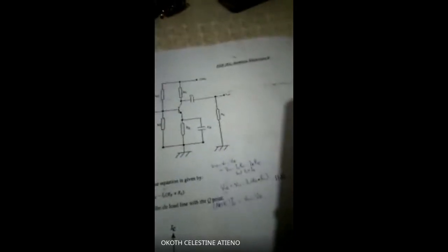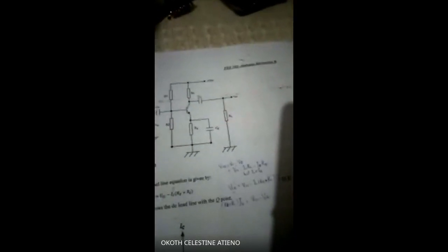Something I'm looking for here. Yeah, this is it. Let me just use this as an example, because the operating point, the Q, is at the center of the AC load line. So you notice this is how an AC amplifier load line will look like. The operating point Q will be here, and there will not be any clipping.